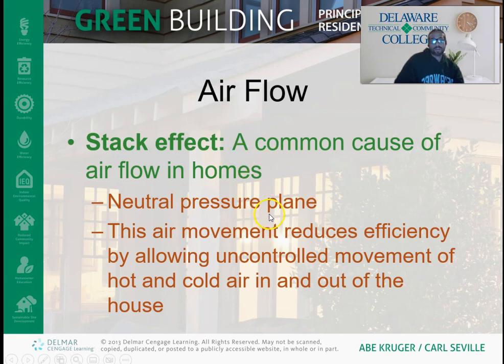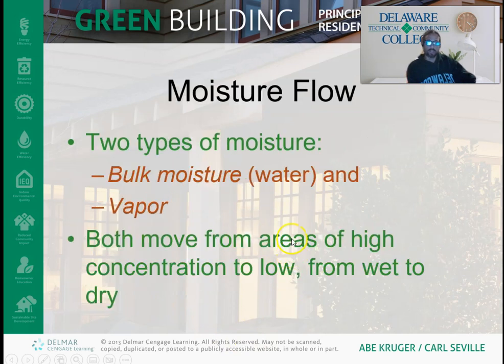And we'll talk about the stack effect in more detail, so I'm not going to get into it here, but they do detail that in your book. It's basically warm air rising, which forces the air pressure higher toward the top of the building and lower at the bottom of the building, which forces air out toward the top and brings air back into the bottom. So I go over this in more detail in a presentation in class.